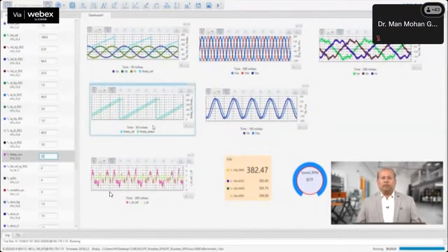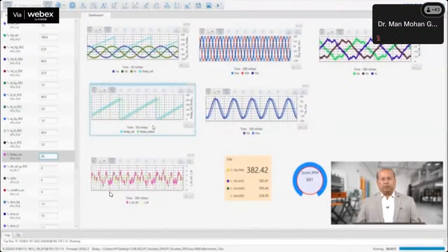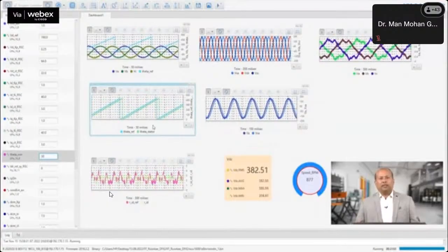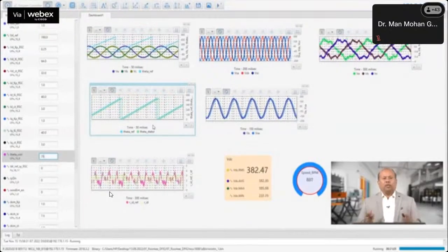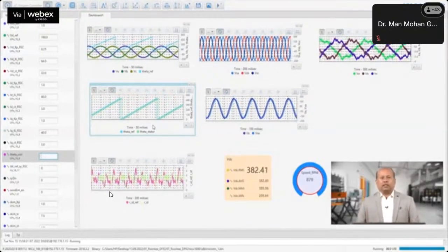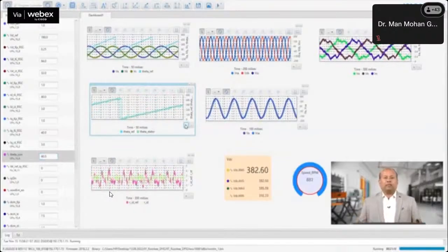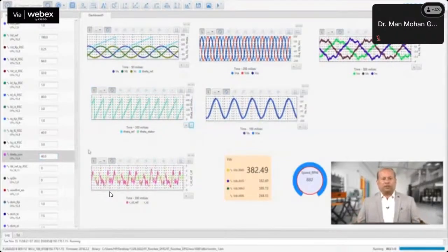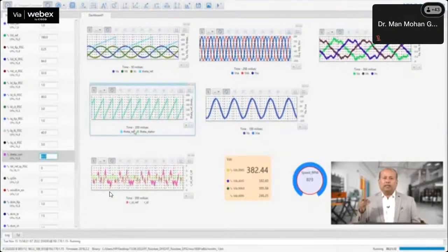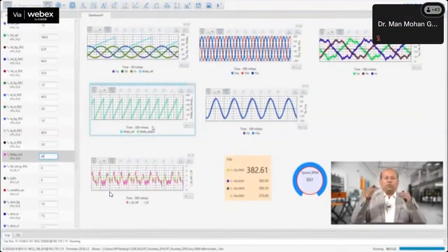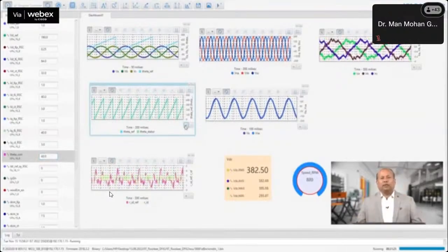The slip is varied plus or minus 30%. So, small current injected to rotor side results in a larger voltage across the stator. Then we vary the Q axis of the RSC to vary the theta. We change the reference till theta is matched. If we see the grid and stator voltage, we see the waveform almost overlap with one another.